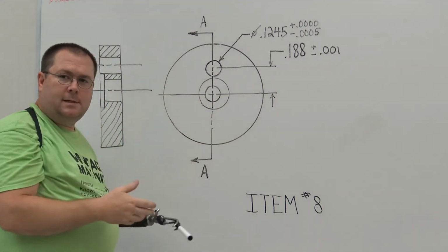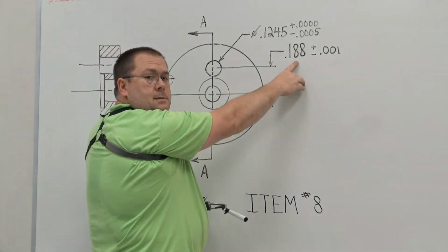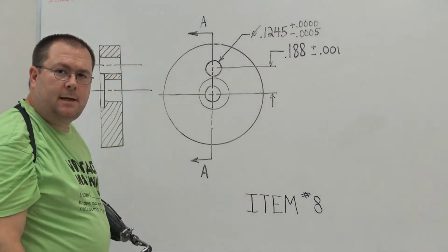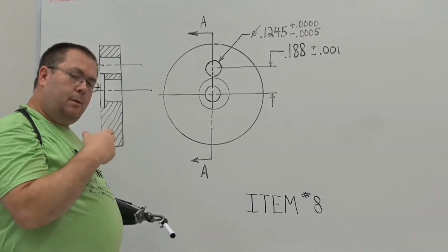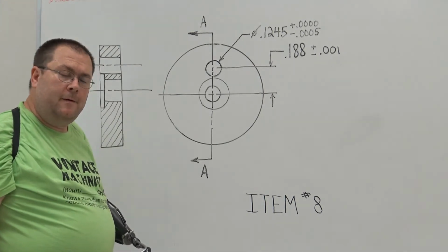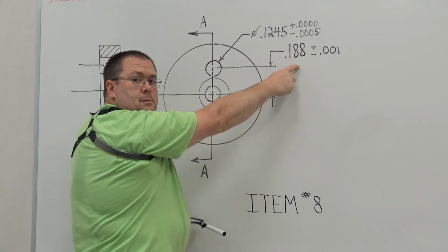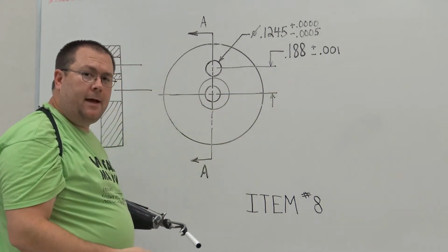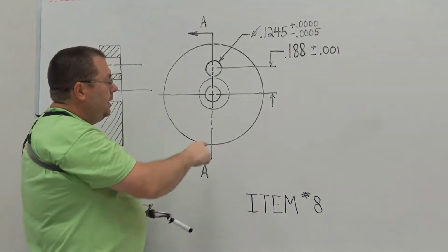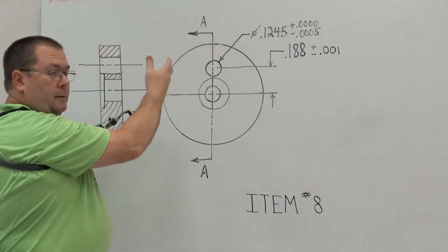You might ask yourself, why is it important that we locate to the center accurately? Well, because the hole that we're going to put in has to be controlled to plus or minus 1/1000th of an inch. So plus or minus roughly 1/3 of the thickness of a sheet of notebook paper. That's pretty tight tolerance. Well, this isn't the hard part. I can dial over 188 thousandths and be well within a thousandth of an inch of how much I've dialed over. It's finding the center of the shaft and the disc assembly.